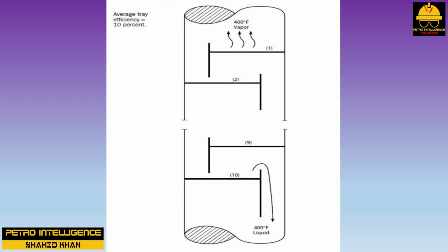As the vapor temperature rising from the top tray equals the liquid temperature draining from the bottom tray, the 10 trays are behaving as a single perfect tray with 100% efficiency. But as there are 10 trays, each tray, on average, acts like 1/10 of a perfect tray.